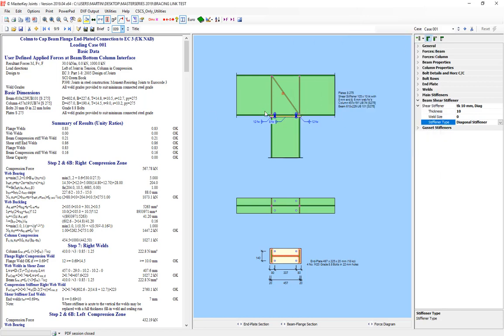So this is very similar to a beam to column moment connection, but transposed through 90 degrees. And in fact, it goes beyond this simple configuration here. You can extend the end plates out, put in gusset plates, even have a haunch, all of which are because it's a sister connection of the beam to column moment connection. So those are the new types of connections.